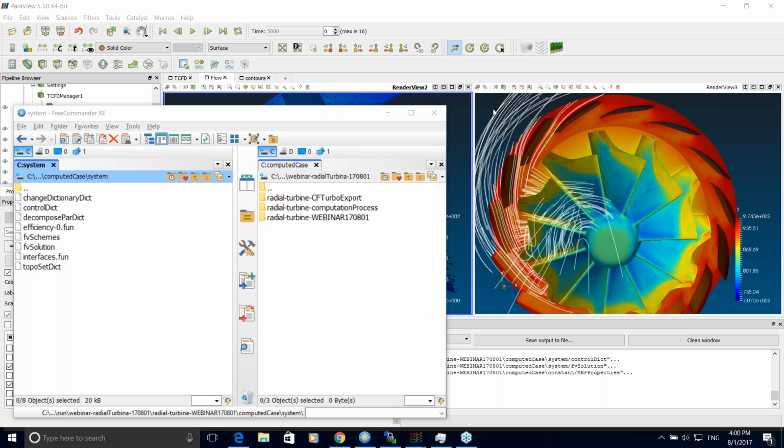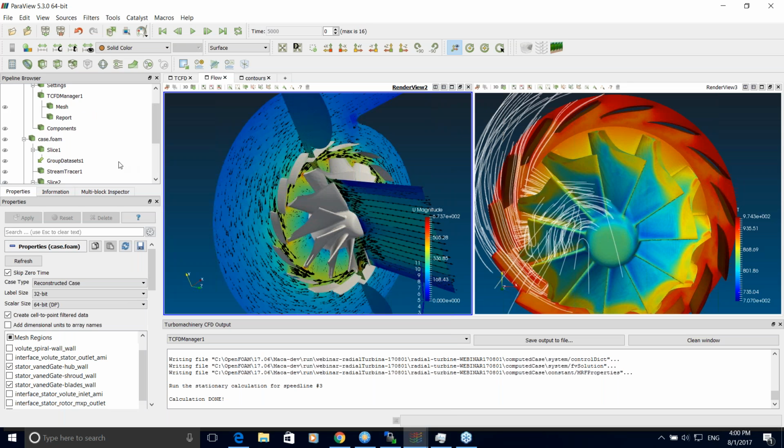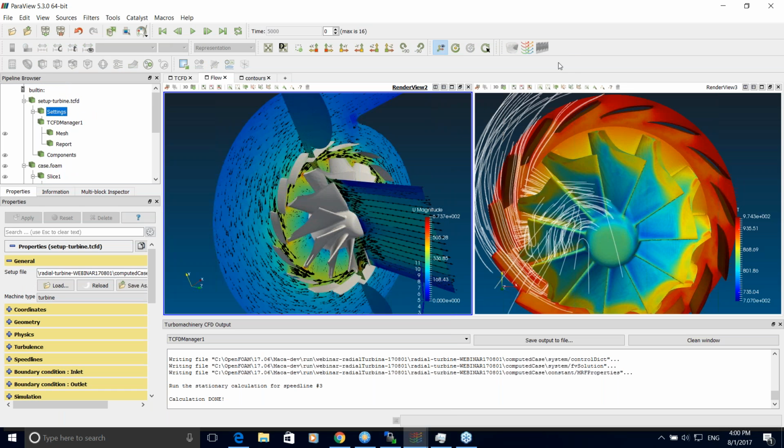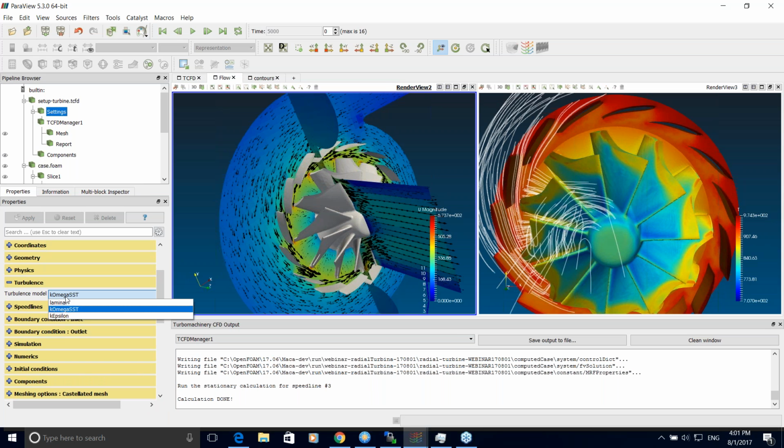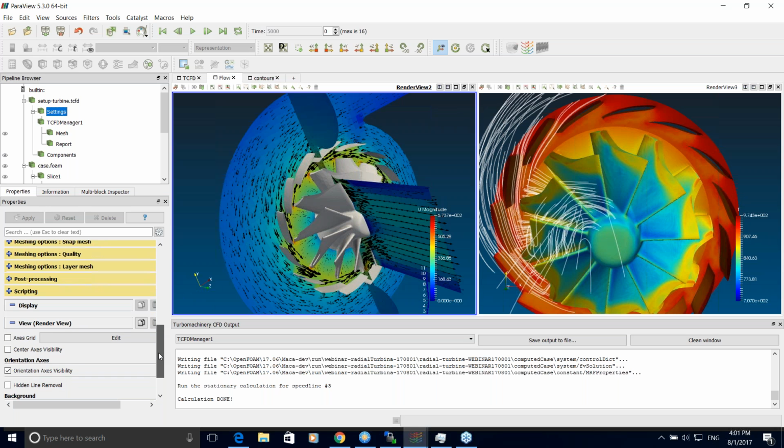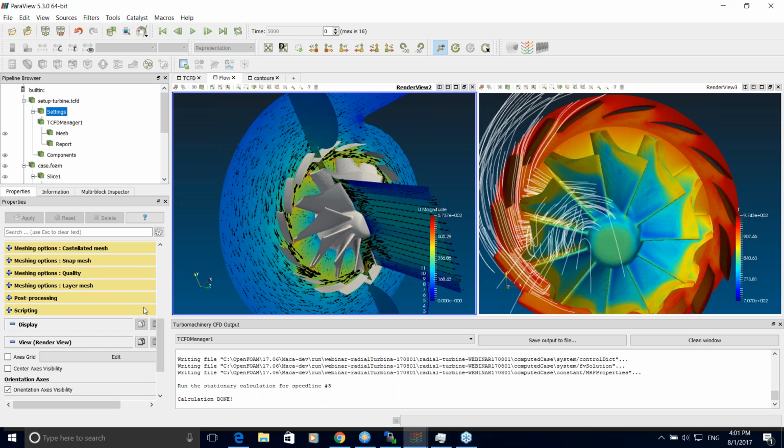Which turbulence models can be used? Radek, would you answer this? Oh yes, I can. Do you see my screen? Yes. Okay. If I go to the setting part, by default we provide three models, or two: K omega SST and K epsilon, and of course laminar, so without a turbulence model. But in general, you can use any turbulence model which is implemented in OpenFOAM, and by